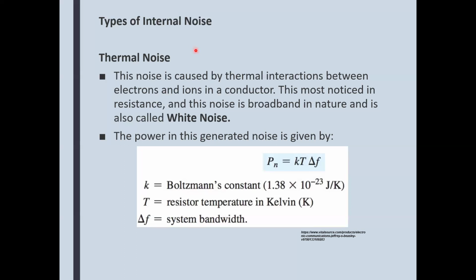Under normal operation, if things are not failing, certain electronic components will introduce their own noise. For example, BJT transistors would introduce more noise than FETs, field effect transistors, because the electrons have to go through certain types of ions and bump into things in the solid state of the transistor.